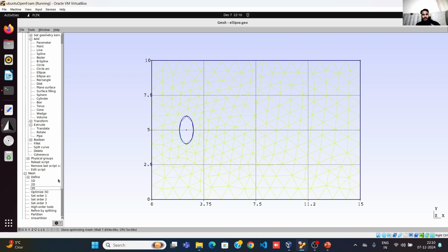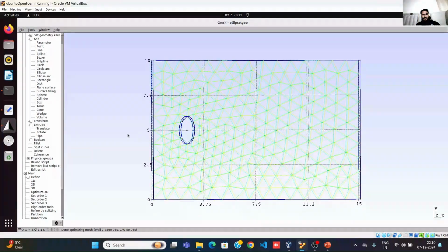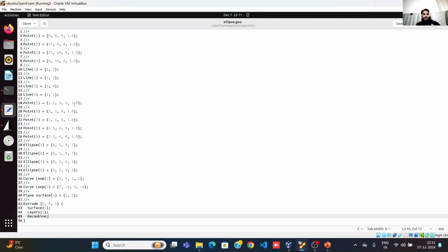like this. Q will be the end selection, and like this we can do mesh along this. As it is course one, so we will consider at the walls of the ellipse I want the denser mesh, so I will consider the denser mesh from these domains. I can do it by saying point, or I can change the code in the script that this part is last one part 1.0 1.0, it is for the mesh space grading. So I will change it from the script at 1.0. I will consider as 0.1 as I want the denser mesh for the ellipse point, that is 0.1.